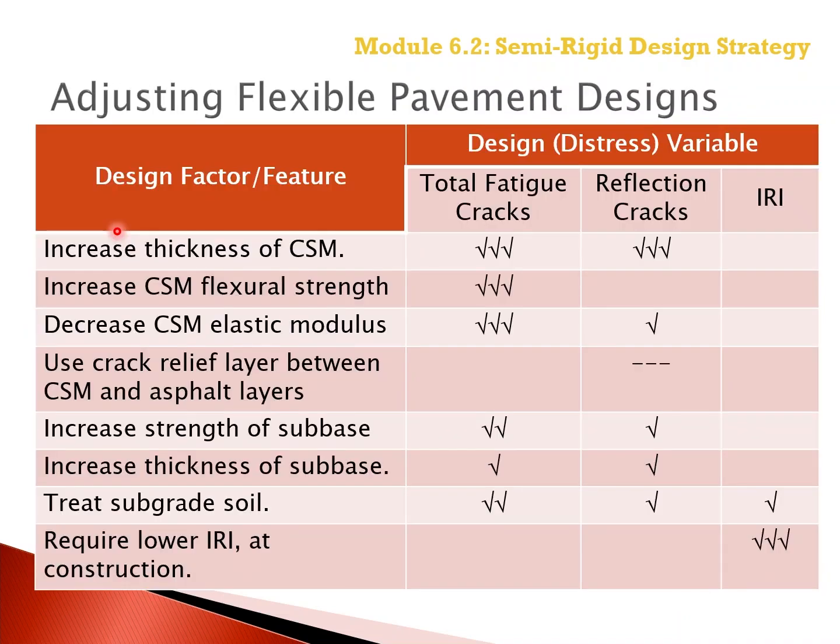The table displayed on this slide simply illustrates the importance of the design factors or features related to the chemically stabilized layers in changing the distress variables. The two distress variables are total fatigue cracks, which would include chemically stabilized layer fatigue cracks and reflection cracks, and then IRI.